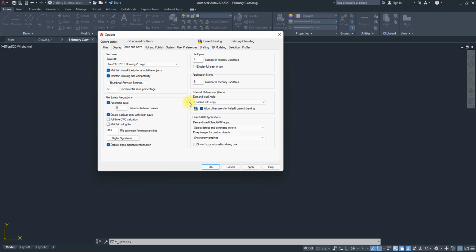So what's this template file? A template file is what allows you to have that title block. Remember when you started AutoCAD, anytime you hit Control N, it opens the dialog for creating a new drawing from templates. When you choose a template, it has a preset title block. You can also create your own custom template with your own title block and save it, so that anytime you want to draw, you can use your own template and start. So .dwt creates a template file, and .dwg creates a drawing file. Those are the two files I'm showing.